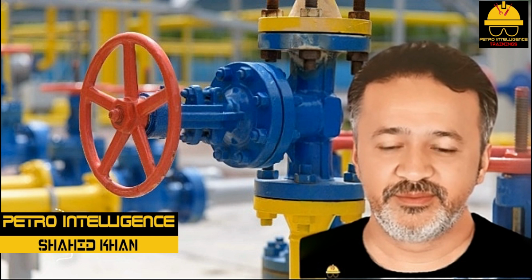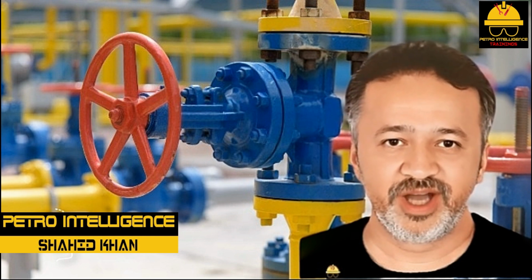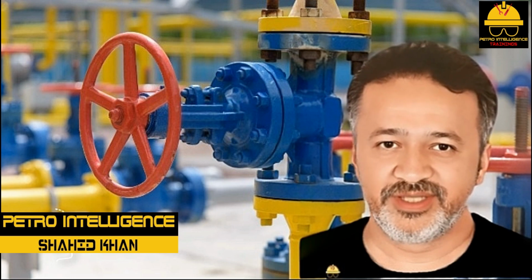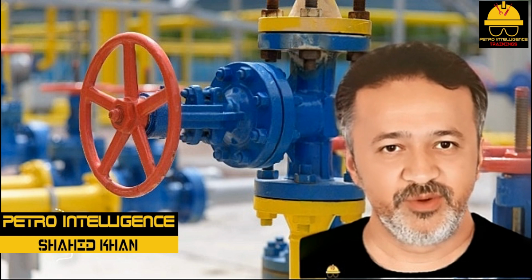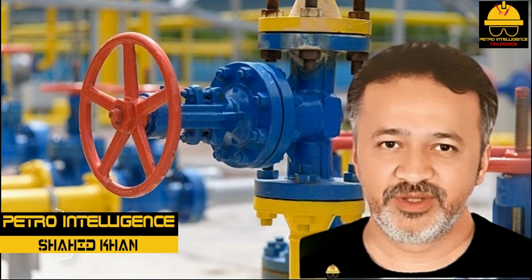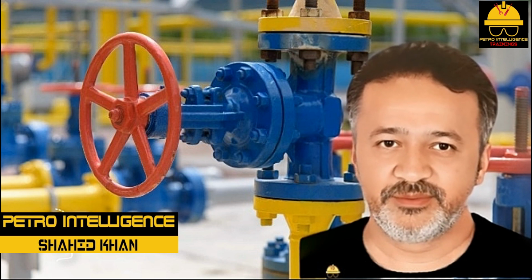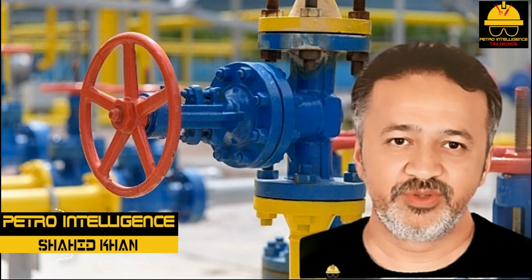Diaphragm valves. In a chemical plant, a variety of slurries, corrosive or sticky substances, are transferred from place to place. Standard valves would have a difficult time with this type of product, but diaphragm valves are specifically designed for the job. Diaphragm valves use a flexible membrane and seat to regulate flow. The handwheel operates just like the handwheel on a gate or globe valve. The stem is attached to a device called the compressor. The compressor pushes on a flexible diaphragm. The internal parts of the valve never come into contact with the process material.